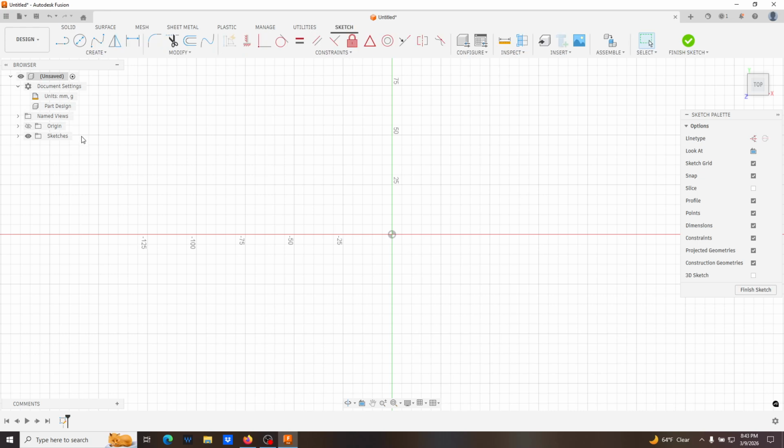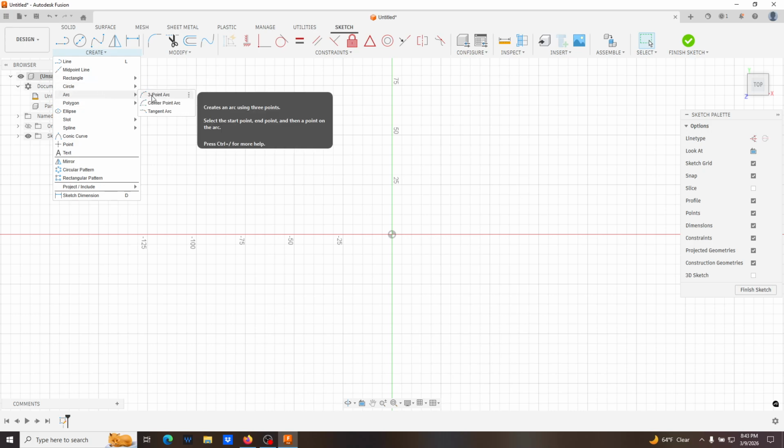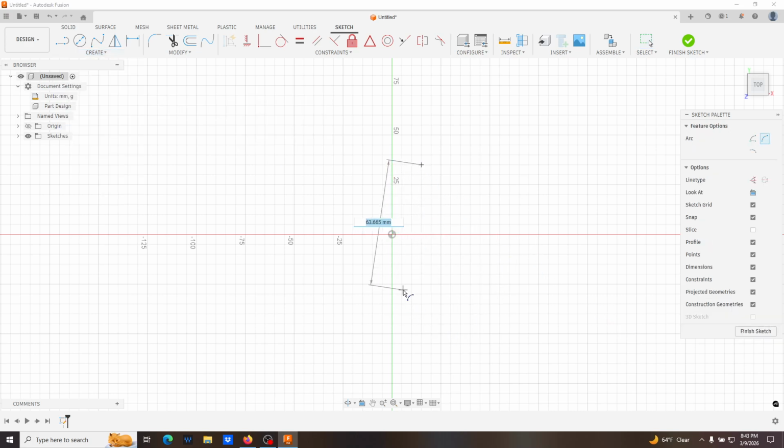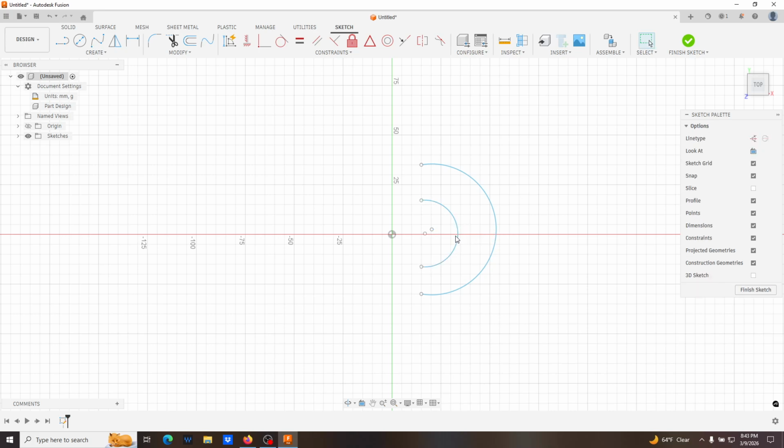Okay. And then what I'm going to do is just go ahead and put the outline piece. I'll just start drawing like I did the first time. So what I'll do is start with two arcs, and I'll just put them around each other like this. Okay, kind of going back to how we finished up part one. And then remember that I can go to the line tool, and then I'll highlight over this, and I'll highlight to here, and those will create those coincident. It kind of put an auto constraint in there. And I'm okay with that.